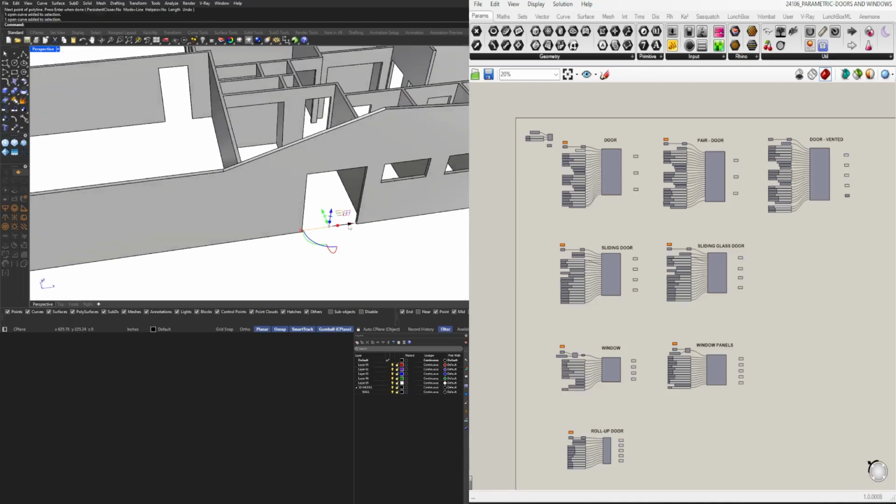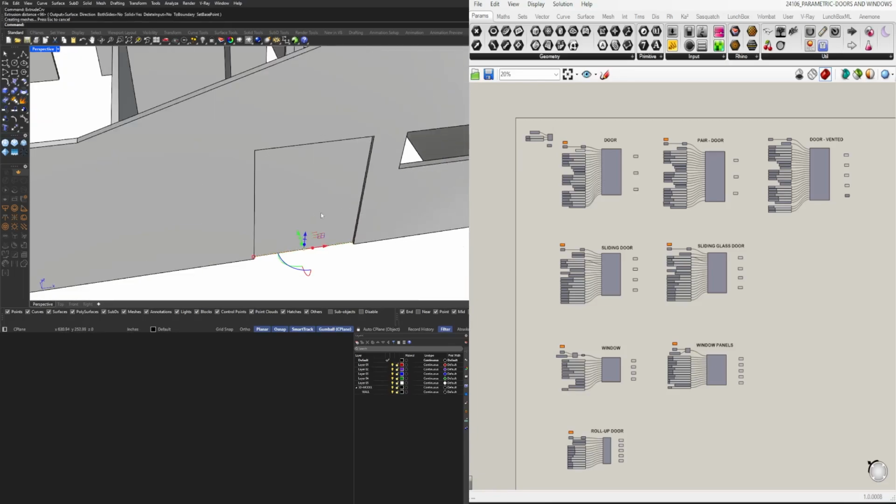So we'll take this curve and extrude it. We'll do extrude curve, or you can also create a plane in the center with whatever other technique you want. But this way you can ensure that it is organized in the way that it will be best received by the script. But you can also apply any orientation surface, or however you created it, you can import it, but you're going to have to switch some things around.